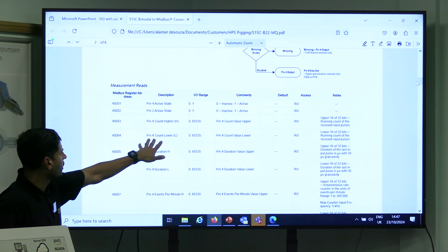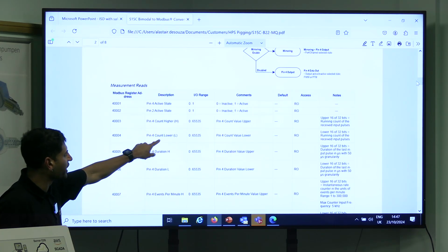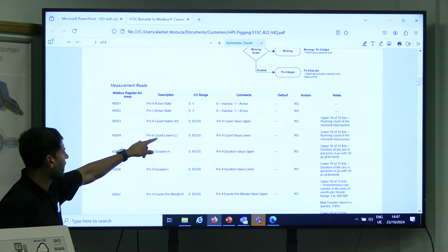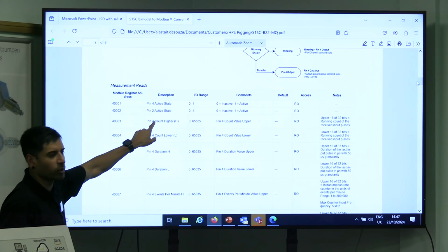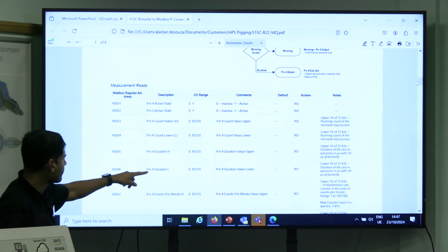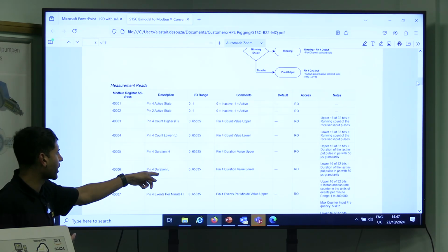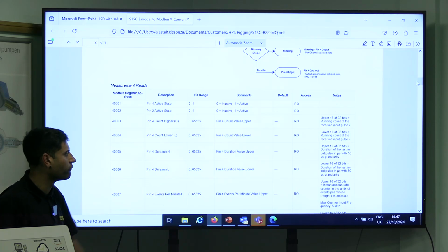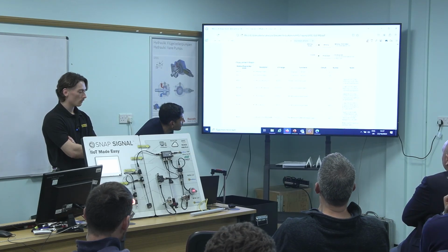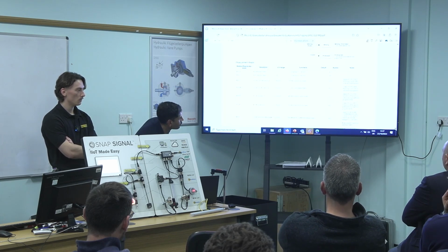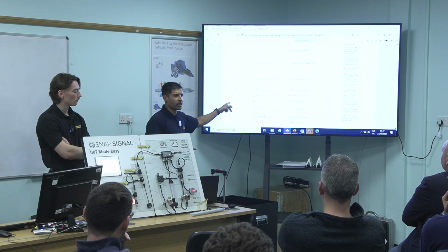So your lower word: when the signal goes from 0 to 1 on pin 4, that will increment, and then when it gets over 65,000, it will increment your higher counter. You can see how long that pin 4 has been energized for, so it does a calculation to tell you how long that's been on for, and events per minute, so that's good for OEE.